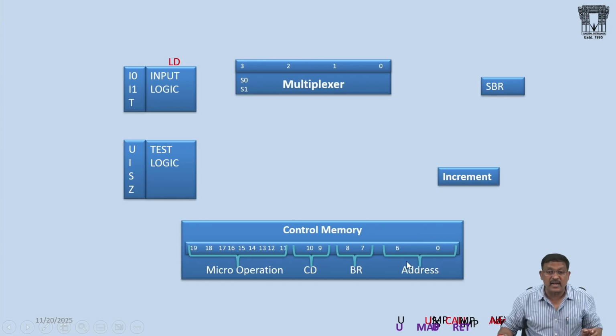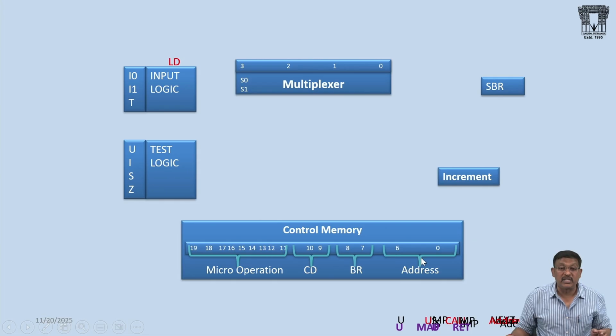7 bits are assigned as address bits. That means 2 power 7 addressable memory locations of this control memory. The power 7 is used to represent the size of the address of the control memory. You got my point? That represents 2 power 7 addressable memory locations, 128 memory locations. My control memory is just 128 bytes.